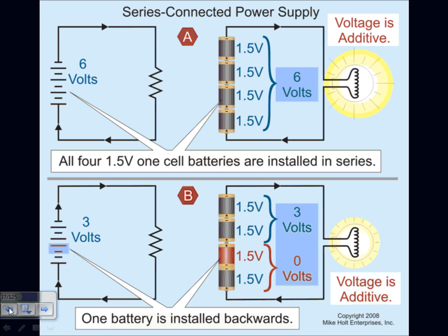The very common example, guys, of putting voltage sources in series is batteries. Now, take this. Some of you might say, Chad, when are we going to see this? Data centers. When you walk into a data center, you will be walking into a room full of batteries like this, 12-volt batteries tied together in series to get you the voltage, and in parallel to get you the current.